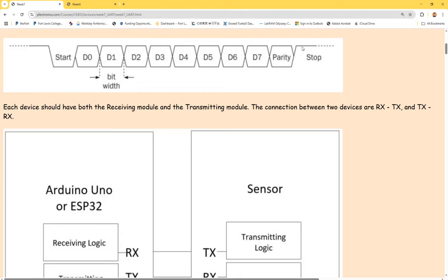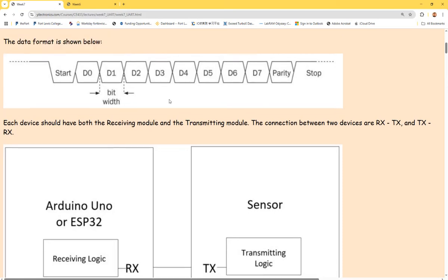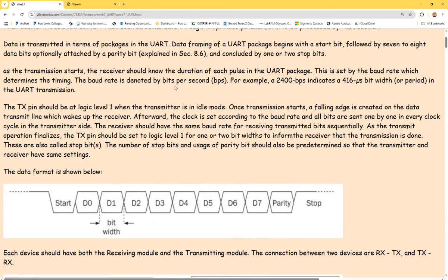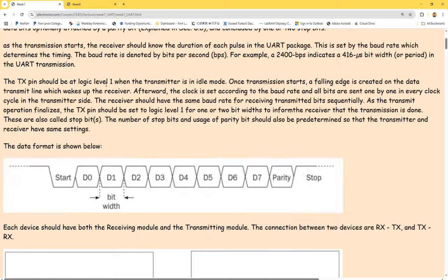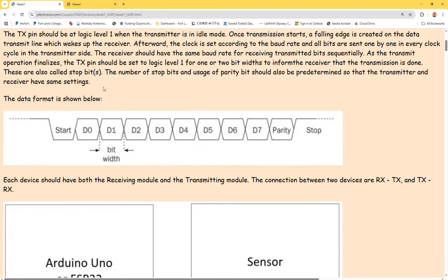It's timed by the baud rate, which is the transmission frequency. The one we use sometimes could be 19200, could be 9600, depending on the certain tasks. Okay, so it's basically doing a count, because we have a way faster clock available on the board, which is 100 megahertz. So you can use that one to count to a certain count number, so we know that it's been 1 over the baud rate, which is the time.